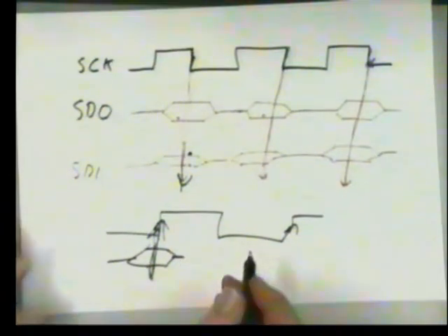using the rising edge as the point where the data is deemed to be valid. So just be warned, you must read the data sheet, you must make sure you have agreed the direction of the clock. But because you're generating the clock using a computer, you can drive it any way you like. You've got to write the program to make it operate correctly. So what I've shown you is how we output bits from one end to the other.